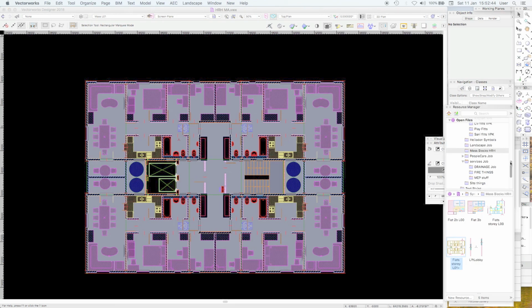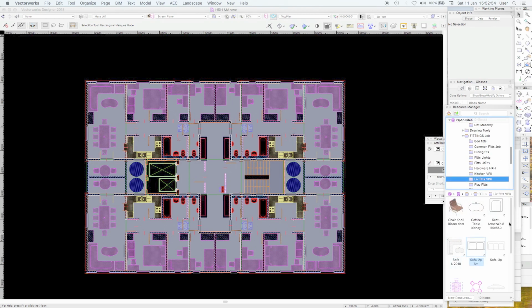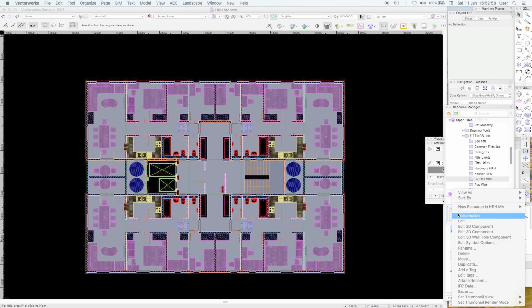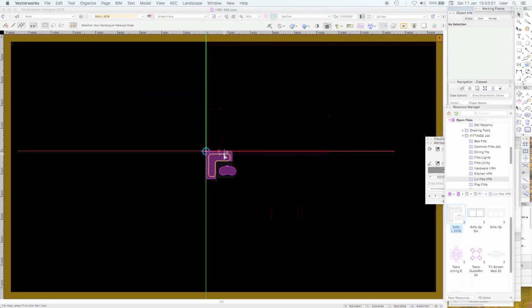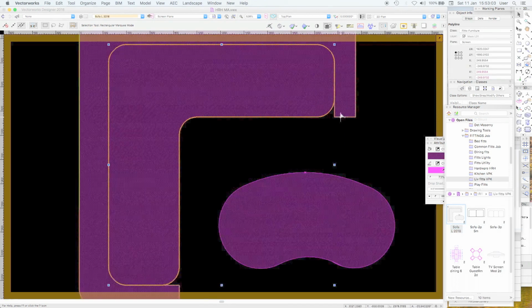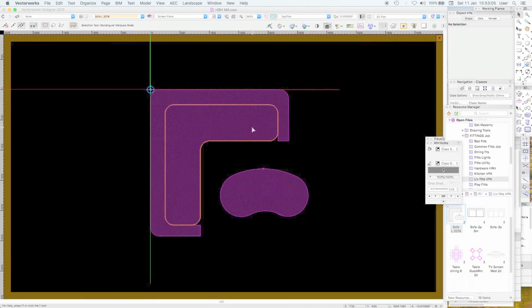the attributes, i.e. the fill, the line weight, the line colour, of all of those things are set by the class. Let's show you what that means. Right, this is a simple 2D symbol, and you'll see that its attributes are always by class. The opacity, the fill, the fill style, the fill color, the line style, the line weight. Now, why do that?